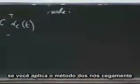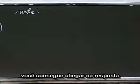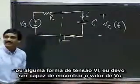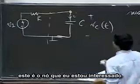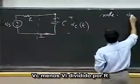Okay, if you just blindly apply the node method and simply grunge through a bunch of math, you should be able to get to the answer. That is, for some voltage VI, I should be able to figure out what VC looks like. So let's do that. So this is the node that's of interest here with the unknown node voltage VC. So let me apply the node method.